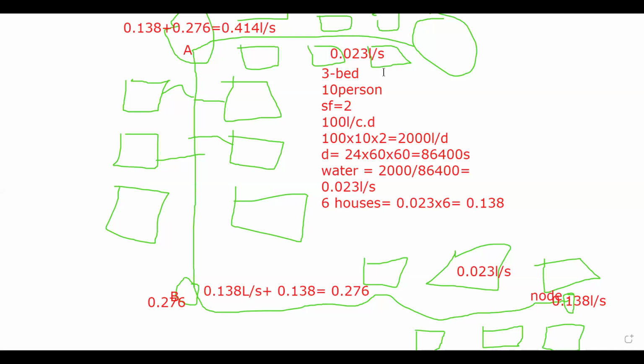You will start at the lowest end. Then as you are going, the pipe is increasing, the demand is increasing until you get to the final. That final will give you the water demand for the whole system. But remember, sometimes you can also break them into zones, phases, branches, and what have you, which we are going to do now. So, gentlemen, if everybody understood this, then we need to go to...